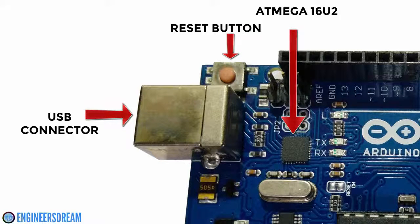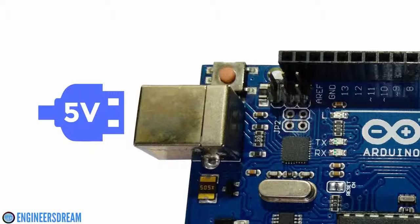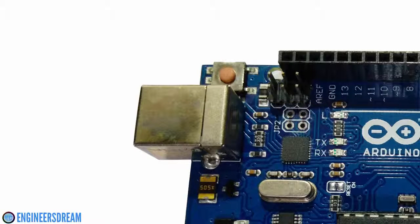The Arduino board requires 5 volts of power for operation, and when we connect the Arduino to a laptop or a computer using the USB, it gets that required 5 volts. Programs are uploaded from the laptop to the Arduino using this USB. Neighboring to the USB, there is an ATmega 16U2 chip. This chip is basically used for USB to serial conversion. On the top, as you can see, the Arduino consists of a reset button. We can use this button to reset the Arduino.